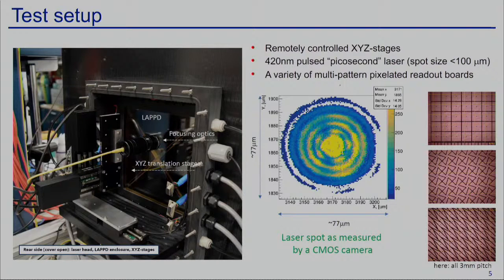We tried various types of pixelations. For this stage of LAPPD technology, these complications make no sense, actually. One can get pretty much the same result with square pixels because the charge spread is pretty large. But it can be different for the next generation, where all the gaps in the stack will be minimized, and hopefully the charge spread will be actually much smaller.